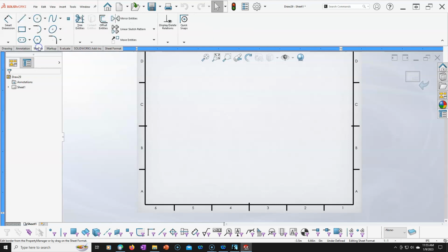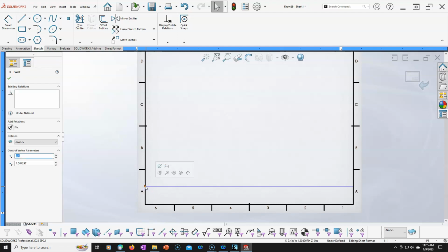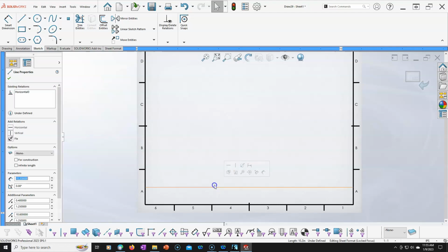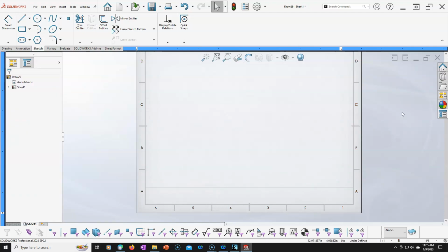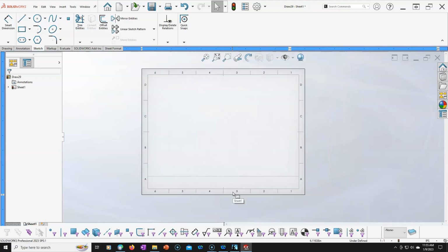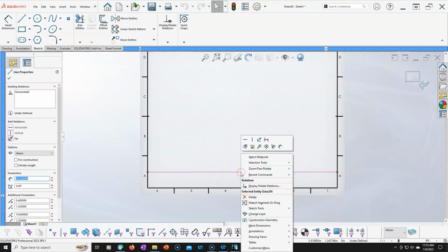Alright, so let's get into the sketch. And we'll place that. So position-wise, X is at 0.4, which should stay coincident. I'm going to give this 1.25 inches for our distance, and no real geometry there. So if I jump out of there, the sheet format, we got the lighter gray, the darker gray, all of the fields. That doesn't look terrible. I would like to make that a little bit thicker.